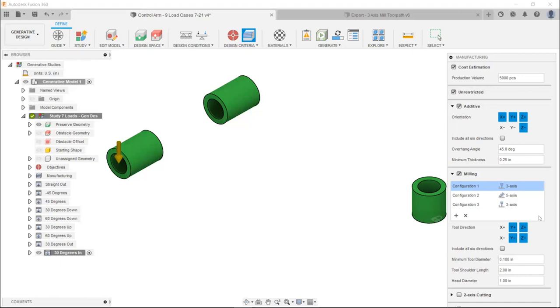So real quick, right? What a 3 axes mill does is the mill can move in X, Y, and Z simultaneously, hence 3 axes. And with 5 axes, usually the raw material can move in 2 different orientations, and that, of course, will give us 5 axes. So with a 5 axes versus the 3 axes, it reduces the number of setups, basically the number of times that you need to remove the material to cut it.